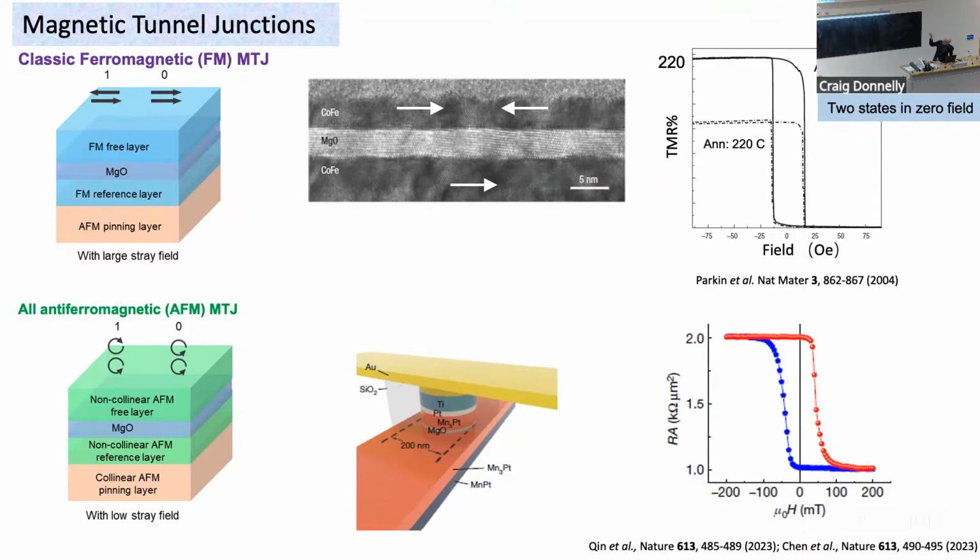So shown in this figure is a characteristic of the type of magnetic tunnel junction used in these technologies. And it basically is comprised here of two layers formed from magnetic cobalt iron, separated by a thin, insulating barrier of magnesium oxide. And these systems, as I mentioned on Monday, show very large changes in their tunneling conductance or their tunneling resistance when you switch the magnetic direction of one of these layers from being parallel to being antiparallel to the other layer. And the change in conductance is related to the polarization, the spin polarization of the tunneling current.